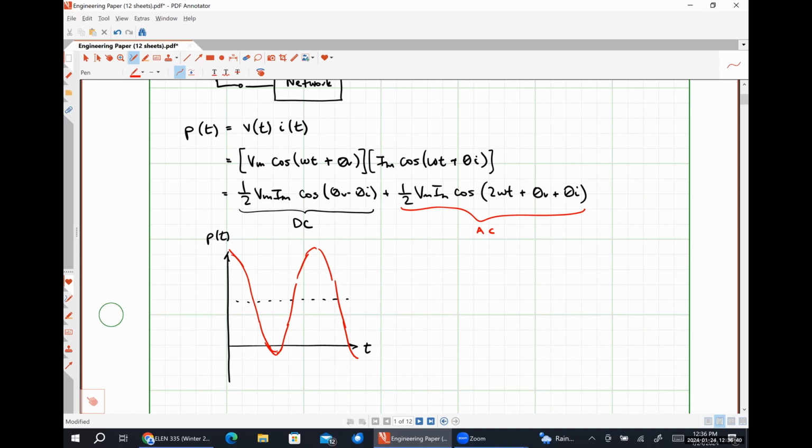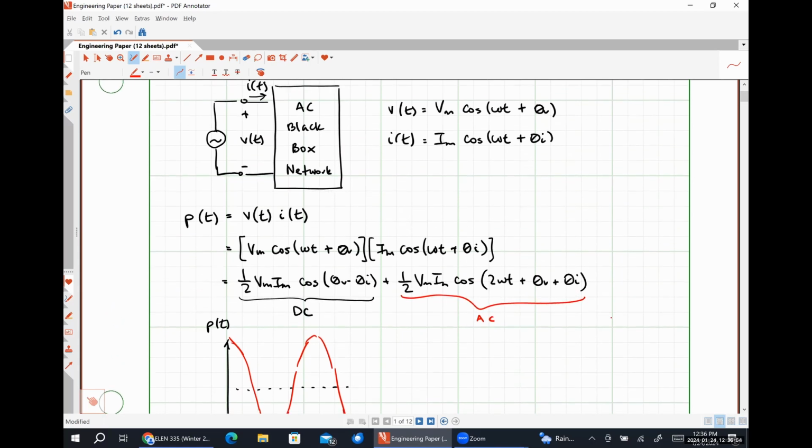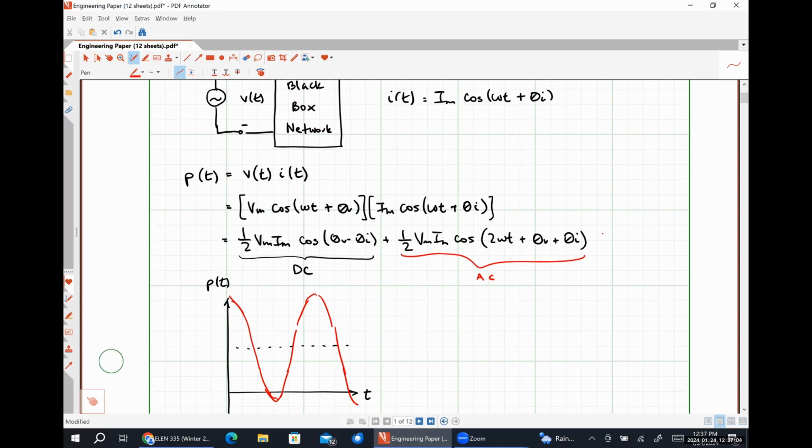Okay. All right, so what does that dashed line bit represent? I'm going to ask my question again. What does the dashed line in this graph represent? DC part, right? But obviously that, because I told you that explicitly, but we have a sinusoidal signal, and exactly half of the time our sinusoidal signal is above that dash line, and exactly half of the time that sinusoidal signal is below that dash line. So the dashed line represents the average power that is absorbed by our load. So this is literally going to be our average power.